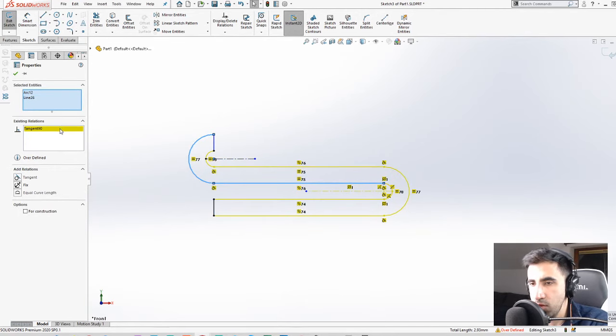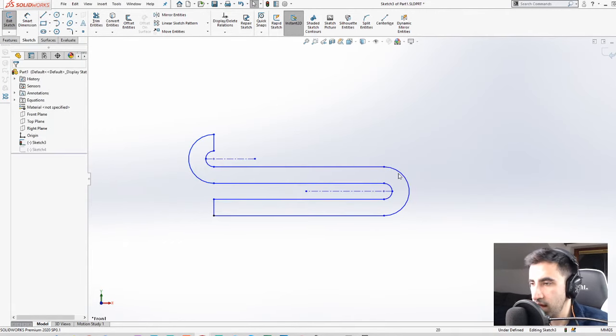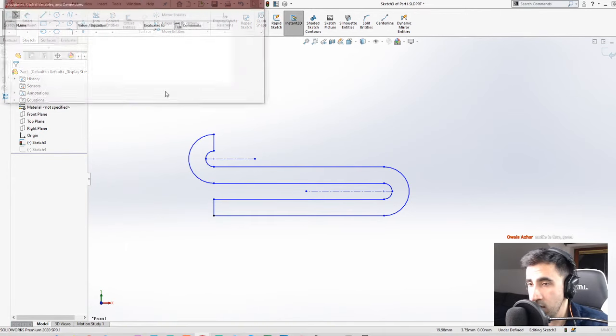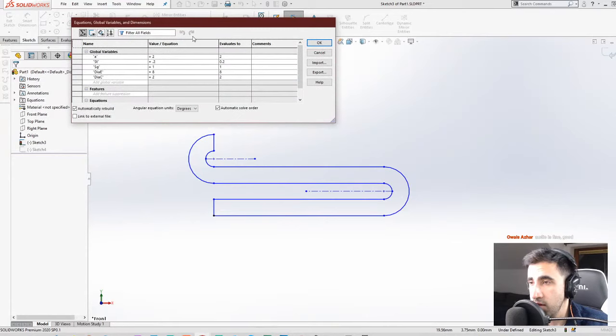Okay, the last one was not needed, so we can get rid of that. Now I think we're set. However, we might come across some errors that we have to go back and edit, but to this point we didn't need equations. From this point on we need the equations. Now you can find equations in tools over here, but I have applied a shortcut to that, which is Control E for me, so do not wonder how this window pops up here. Every time you see this, I'm pressing Control E.